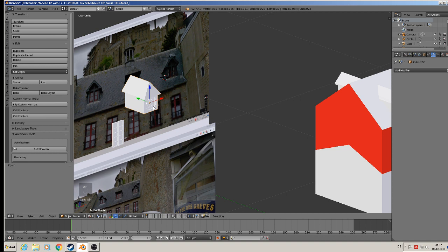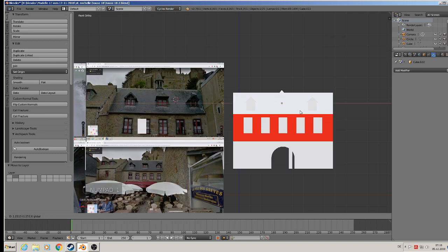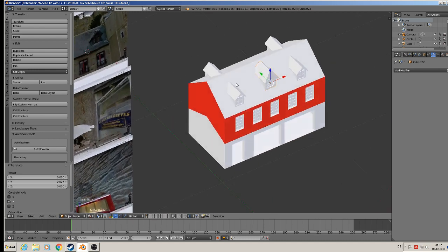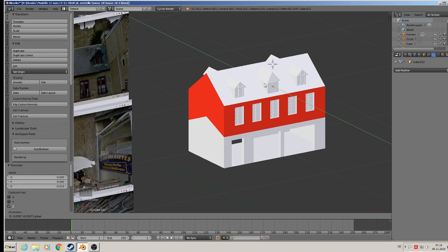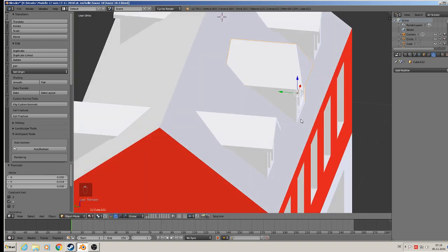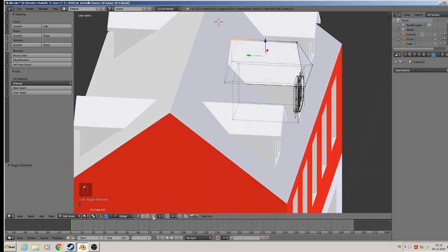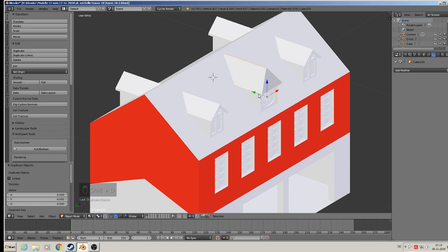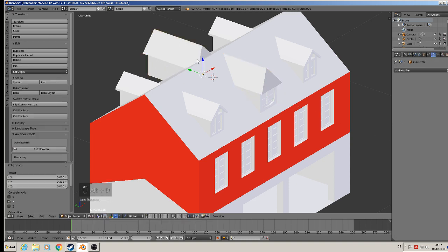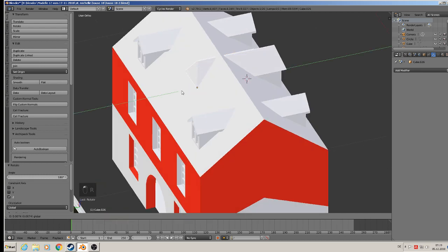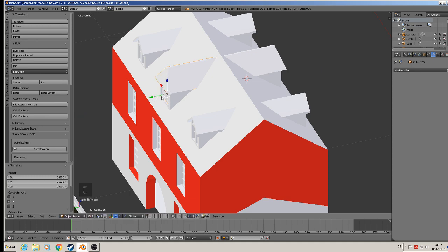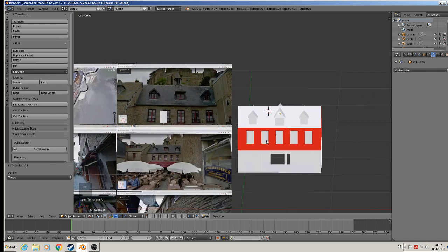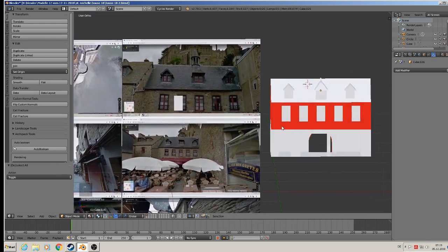Then we take the other one, join that together, Shift D, make a copy, M to move to second layer, get this one on the house roof. And here's the same. Must be long enough. So we take here word selection, background selection, border selection, and bring them more to the right. So that is done too. Shift D, oh, not Shift D, you know it, Alt D, rotate, set 180, and bring it on the other side too. Good. So that is the house in basics, not finished, but near on.